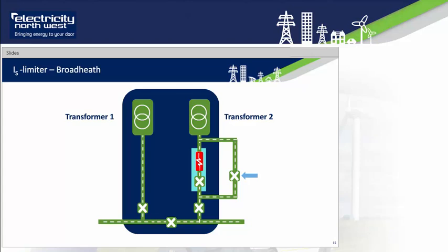If the fault level is exceeded for any of the circuit breakers at the substation, the fault level assessment tool will enable the IS limiter. As before, if a fault then occurs, the IS limiter will operate in 5 milliseconds and effectively open the transformer breaker at the substation, which reduces the fault level any of the circuit breakers will see, therefore operating safely.